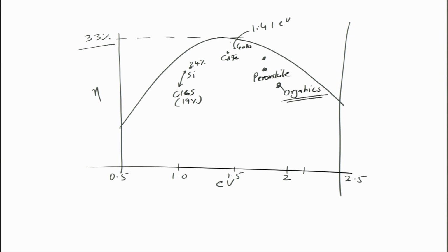I will show you a chart later on in the next class, which can give you a good idea about the devices. So, this sort of completes our discussion on device parameters. We started with the analysis of p-n junction in dark, then we looked at p-n junction in light, and then we looked at solar cell device parameters. The idea is to have as square or rectangular an IV curve as possible with minimum parasitic resistances, and we have to optimize the band gap to maximize the VOC. So, we will stop here today.